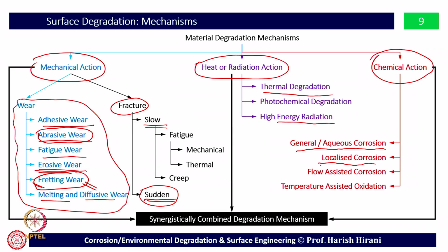Any other surface degradation phenomena will create more problems. One is a local one, maybe at some place some sort of fault remained, and then slowly the corrosion starts from that place. Some extra stresses are generated at that level, or some sort of acidic action, then there will be a problem. Flow assisted corrosion is naturally flow related, and with the flow, mostly because of the water, the corrosion will occur.